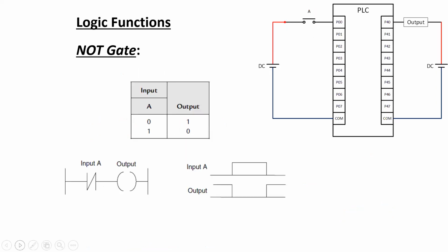So that is shown over here, that you can use a normally closed contact in series with the output coil. Now, even if the switch B is connected, you are not removing it from the external connection. Still, your operation will go on smoothly, because in the set of instructions you are never introducing the address of this particular port. So even if that is connected, that is not going to hamper the operation of the CPU.